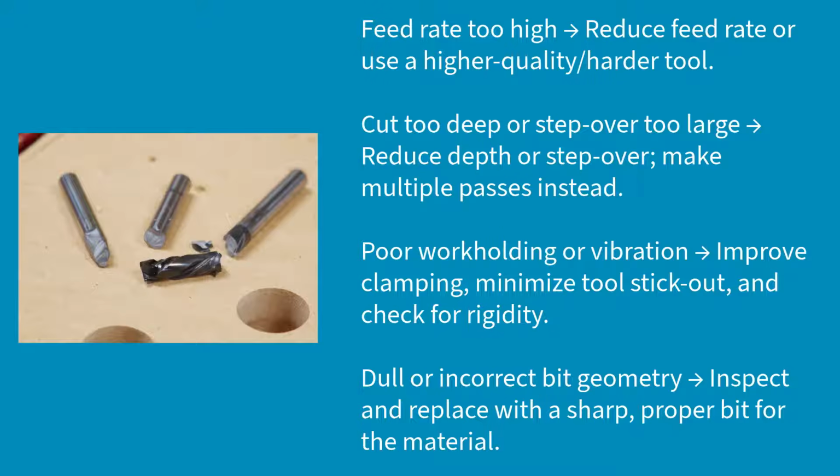I would say this is probably the one that I see most often, is that the depth per pass is too high. So you want to try reducing that slightly and seeing if that helps, especially if your bit is breaking. The other one is poor work holding or vibration. So if your tool is not sitting tight into the collet and clamped correctly, you can see your bit moving inside the collet, and that can cause vibration or it's not held enough, and then it'll break. We have a video on how to set your bit into the collet, which we will link below, so check that out if you have any questions about how to do that appropriately.